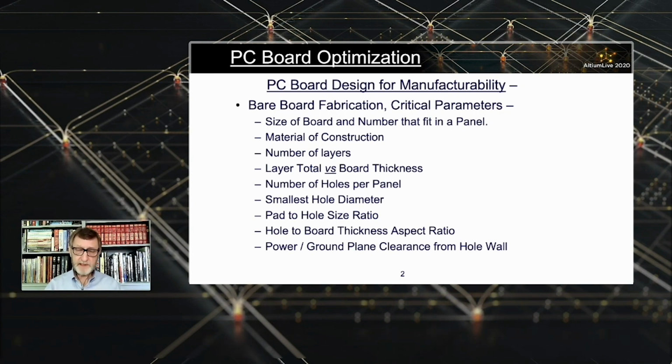We could have put 12 layers in 62 mils, but it would have changed things to the point where it would have made the fabricator's job more challenging, because a 50 ohm line would have been a narrower trace. And narrower traces are harder to hit with controlled impedance. It's just that simple. So the point I'm making is, think carefully about what you're doing when you choose a board thickness. Drive into the mechanical people's heads, the boards aren't all 62 mils thick. If you're going to mount boards on 4 screws on standoffs, or 8 screws or whatever, they certainly don't have to be a defined thickness. They can be whatever you need for them to be. Make sure everybody's aware of that and work with that.